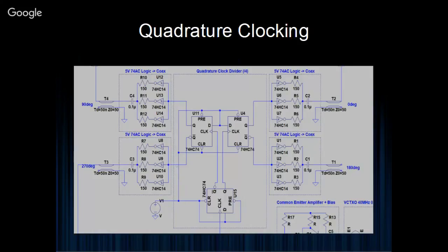Sorry, it's a short circuit at very high frequency AC. So there's a limited number of gate inputs you can drive from one output, and that concept is called fan out. You need to make sure that the picofarad limit of that output is not exceeded by the sum of the gate input capacitances.